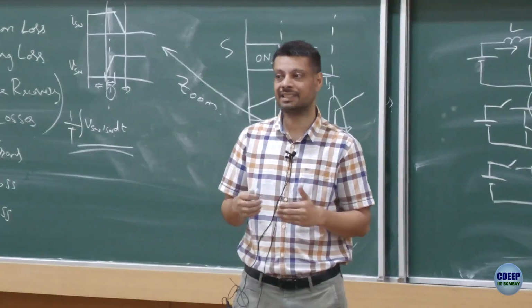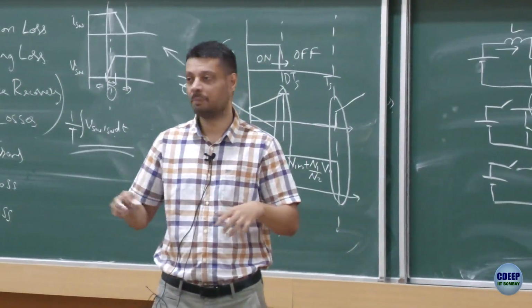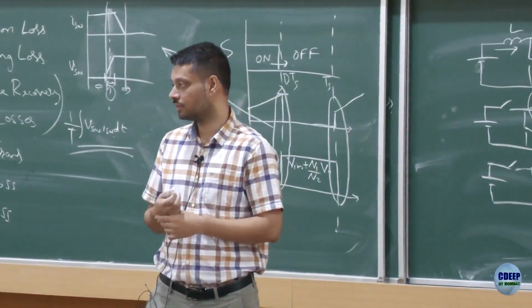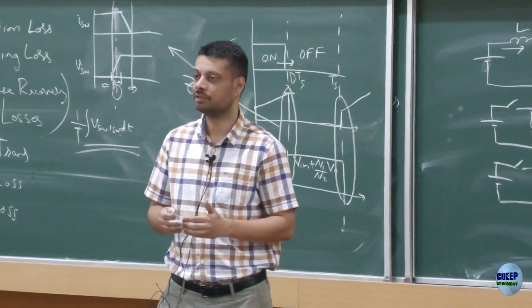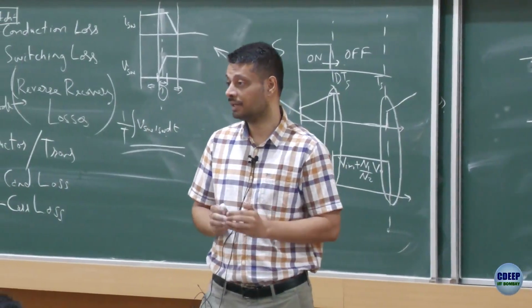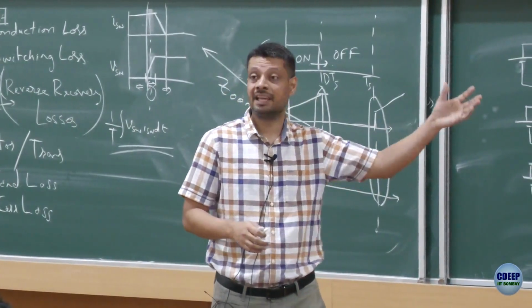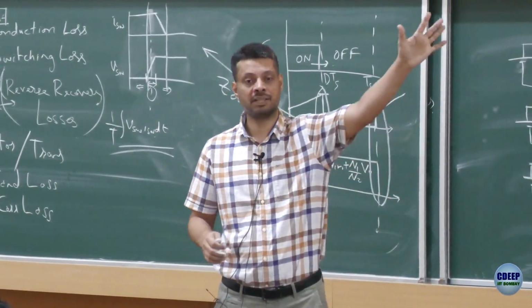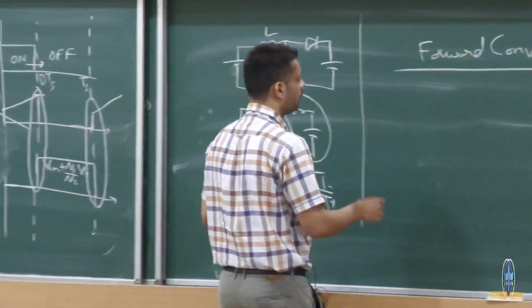So that is the reason, it's not like A is always better than B, it depends on your application, on your situation. How it usually spans out is that for lower power, flyback works out very, very well. As you increase the power, slowly you shift from flyback to forward, and then from forward to a few other circuit topologies, whichever is more economical to operate.